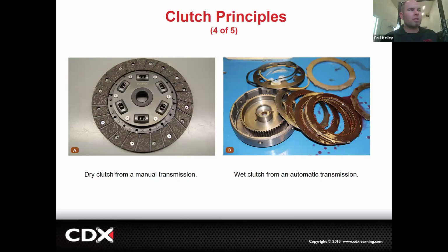So there are clutches that look like this that we don't have to control with a foot pedal. But a lot of the dual clutch transmissions, they'll actually use wet clutches too. So in the dual clutch, it'll actually look like a manual, but the way that the odd gear shaft or the even gear shaft is applied is actually with wet discs, which means we're applying and releasing those with hydraulics, just like in an automatic.